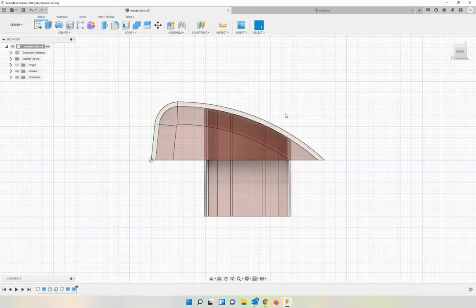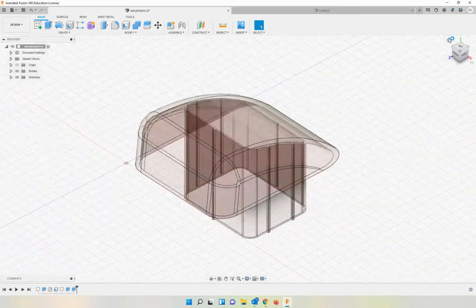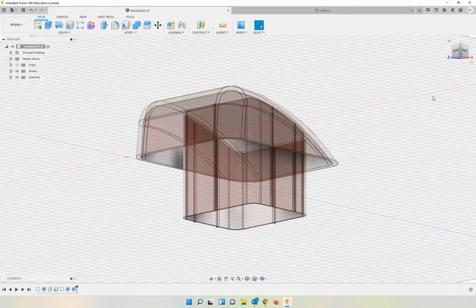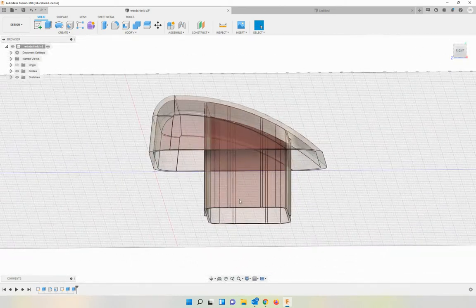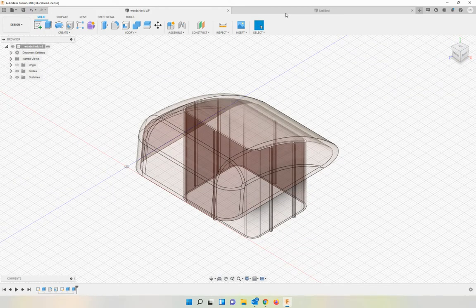Viewing from the left-right view, we'll extrude that to the width and shell out the design and add the insert, this part that comes down, that fits into the cutout of the passenger section. All right, let's get started.